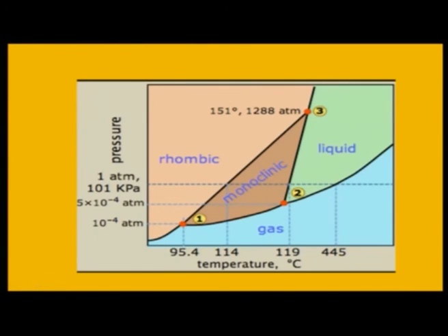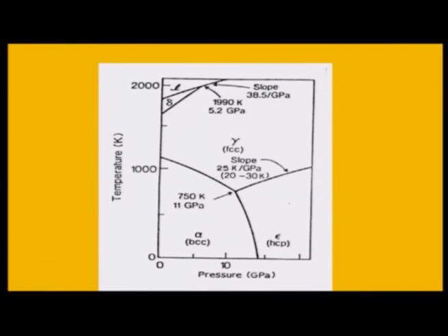By this I just wanted to show you, at the end, the phase diagram of iron, which I have already shown to you. See, iron has alpha phase, gamma phase and delta phase. Alpha and delta are BCC, gamma is FCC. And this is actually beta, known as HCP phase, at a higher pressure of about 18 gigapascal. This HCP iron is present at that pressure, and at a very high temperature it becomes liquid.